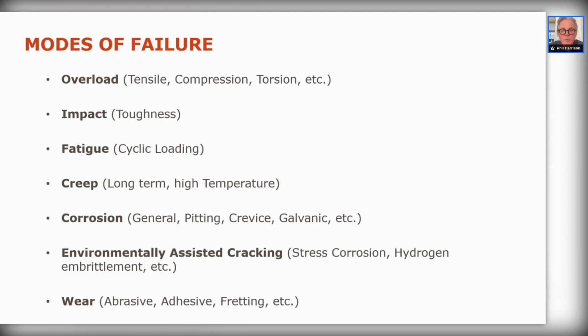Then we have hydrogen embrittlement. Hydrogen, a very, very small atom, can diffuse into materials and then can push them over the limit and form cracking. For example, with stress corrosion, we might have something where the internal stresses are within a limit. Hydrogen can permeate in there and you can form stress corrosion. This is then called hydrogen-induced stress corrosion cracking.